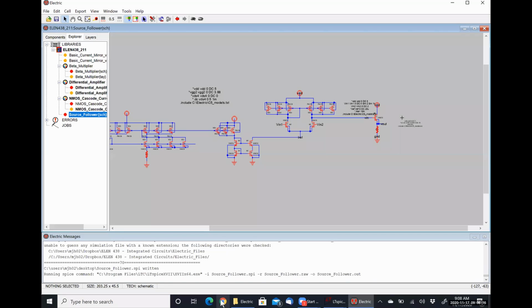Okay. What if I can't do that? Do you have any suggestions for that? I mean, you can't. I would say load the servos less, because the servos are going to draw X amount of current regardless of whether or not there's a capacitor in there, right? They need so much power to turn.